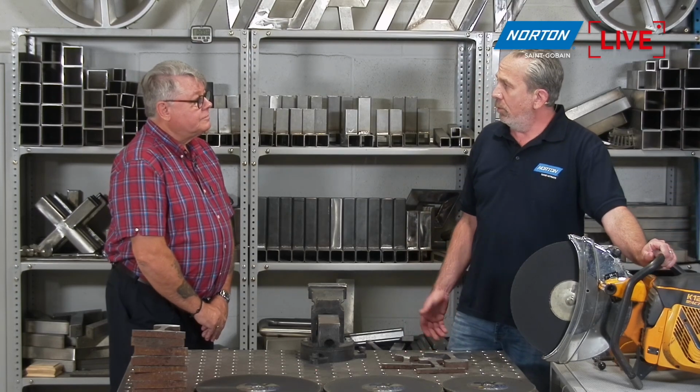Okay, so back to us in the studio. So Ian, as we discussed there, rail cutting and why. This is the type of machine we're using, a petrol saw. So why would we be using a machine like this for rail cutting? What's the reason to use a petrol saw rather than a corded grinder, for example? Well, this is the industry standard worldwide. Most rail companies now use two-stroke rail cutting saws because they're an independent, lightweight machine that's easy to carry to site.